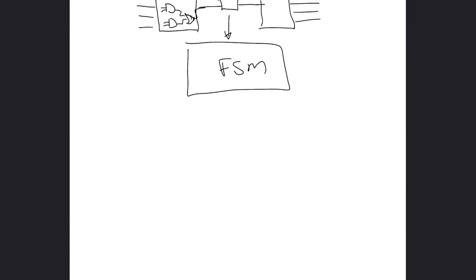Just to be sure we're on the same page, this transmitter drives 3 things. It drives an output enable for the counter. Sorry, I'm lying. An output enable for the tri-state. It does a counter enable. And it also does a shift enable. So those are the 3 outputs you need to drive.